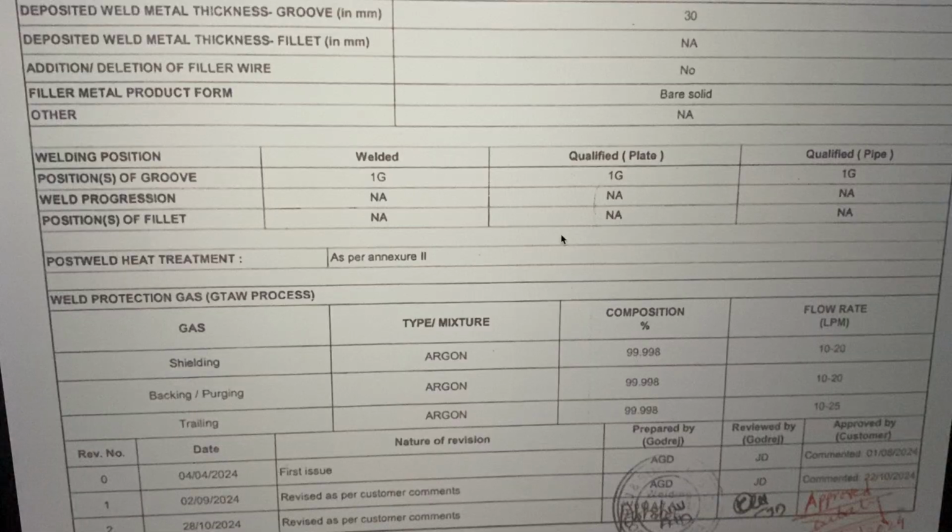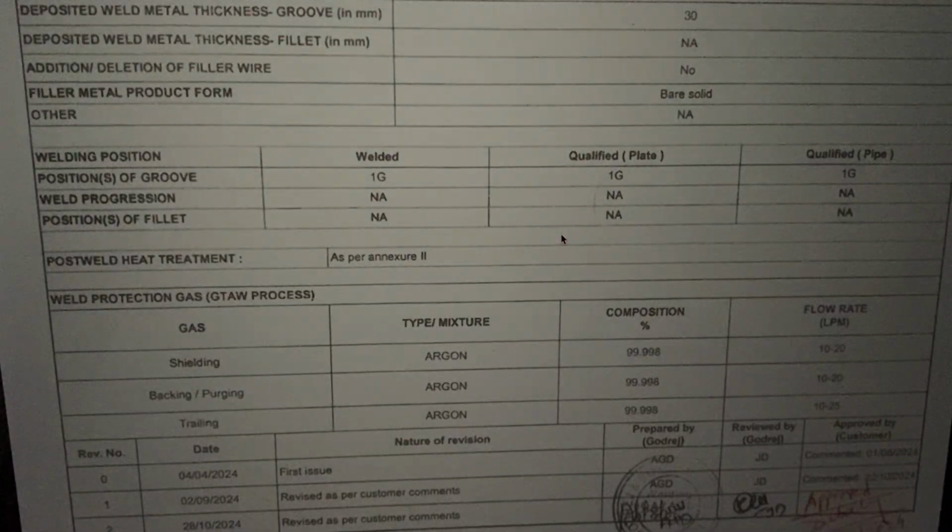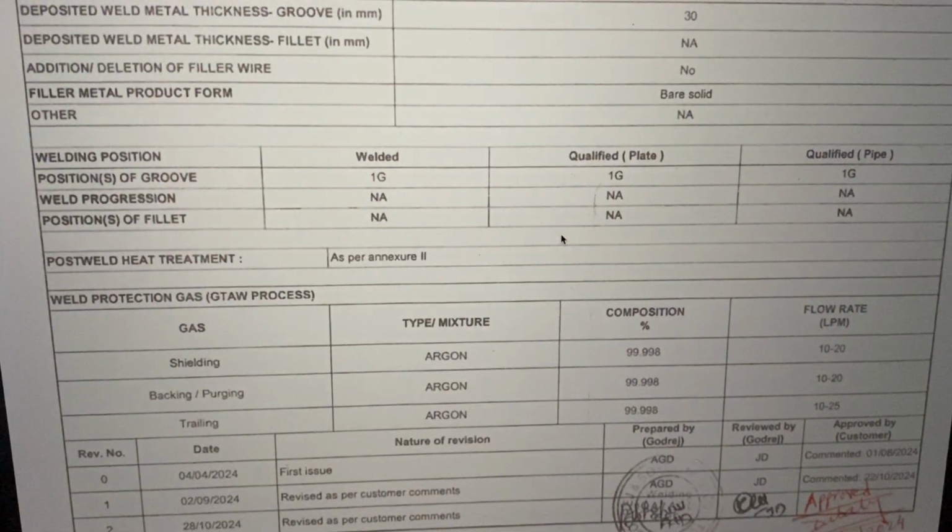Code is giving us that permission, but always we gain confidence by spending a little money upfront, because it is not only achieving properties. I think it is finding out what kind of setup requirements are going to come. Can we penetrate a gap of 2 millimeter with the set of parameters we have chosen, or how are we going to really get the distortion levels, what kind of fixturing is required for this joint. All that information, very good information, comes in handy when we have our own WPS and PQ.